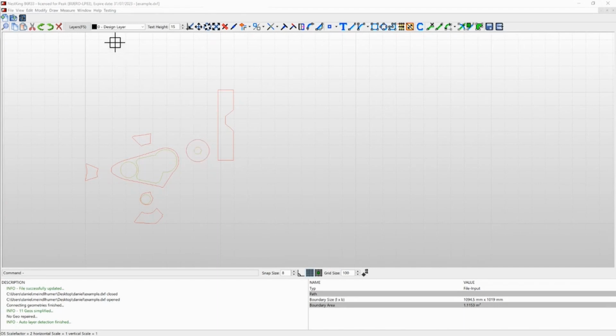Here you can select between layer 0, the design layer, just supporting you for generating cuts. Geometries and text on this layer have no influence on the cutting generation process itself and are also not considered for nesting. Next, layer 1 is the so-called text layer. Same as with layer 4, texts on this layer are printed by the cutter downstairs and can be used to label the cuts. Layer 2 and layer 3, as already mentioned, are inner and outer geometries, and these layers are interpreted as cutting lines by the cutting machine.